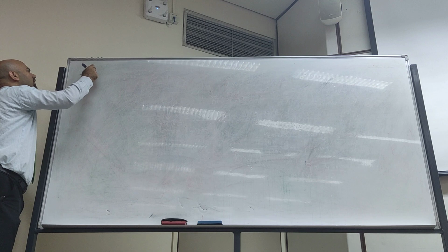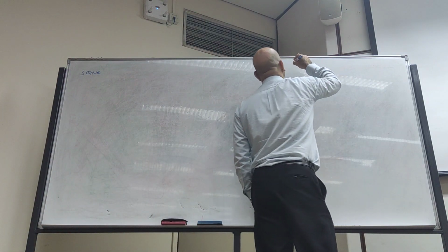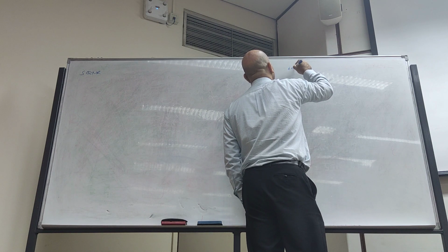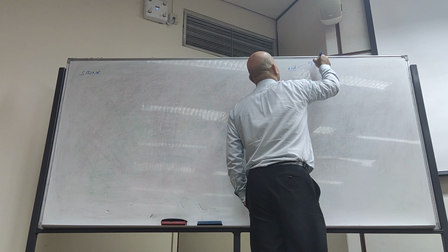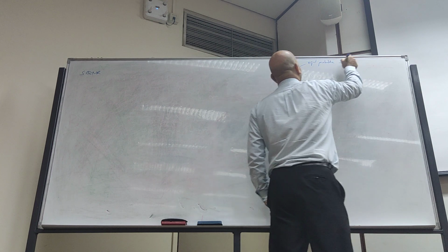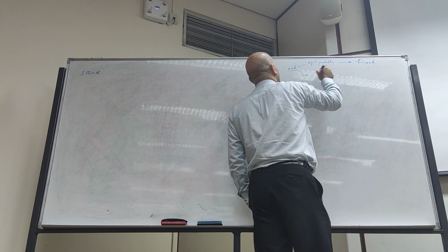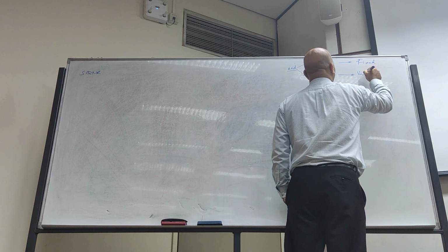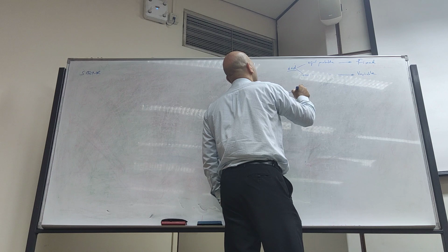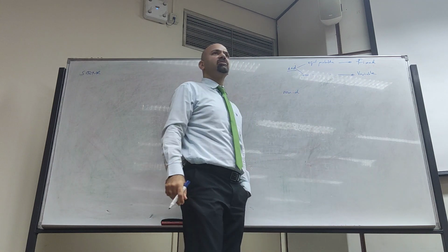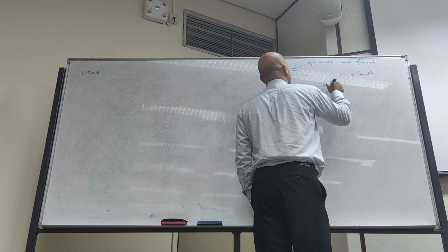Whenever we saw last time the SQNR, okay, let me make a larger review. So we said that whenever we have IIDs, and the IID samples are equal probable, we go for fixed encoding. Whenever they are non-equal probable, we go for the variable Huffman code, right? Then we have the other case whenever they are non-IIDs, so the samples depend on the previous one and so on. What to do? Whenever they are equal probable, PCM.